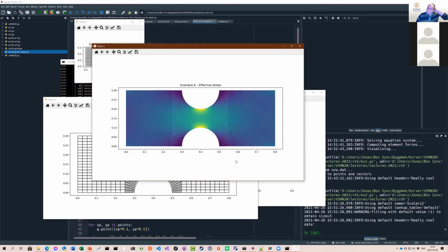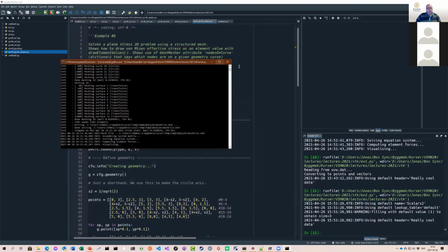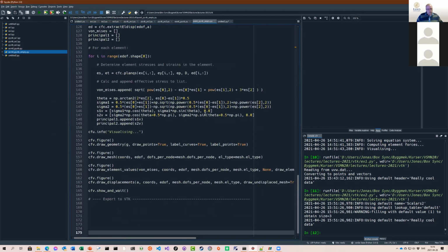So in some way we need to convert the data we have calculated and create a VTK file containing all of these things. I have prepared a recipe for this, which I will do step by step now. The first thing we need is to create the points that will be used in the VTK export, and the polygons. Unfortunately, the pyvtk toolkit doesn't take NumPy arrays as input, so we need to convert the NumPy arrays to lists, which is quite easy to do.